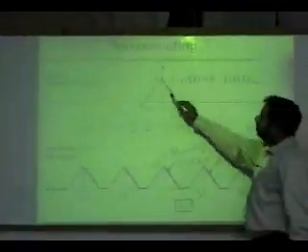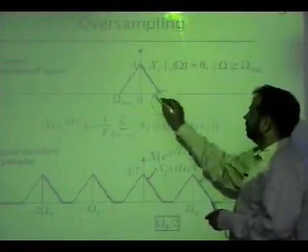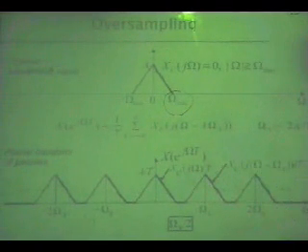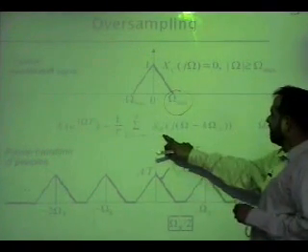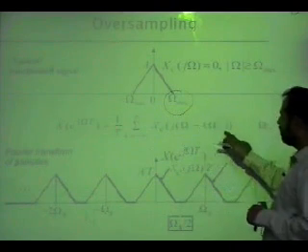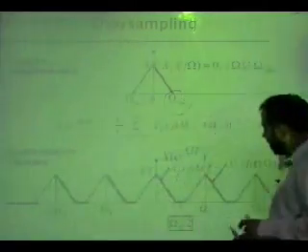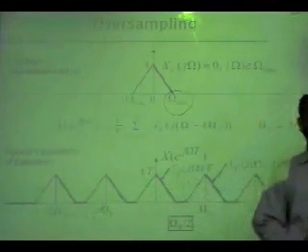But coming back to this slide, we said you assume that there is a maximum frequency and there is nothing beyond this maximum frequency in your signal. If there is, you clean it out in the analog domain. Then we said the sampling is really making copies of the spectrum Xc(jΩ) at every Ωs. And this is the mathematical interpretation, that you are making copies of the spectrum at every sampling frequency, Ωs, 2Ωs, minus Ωs, minus 2Ωs.